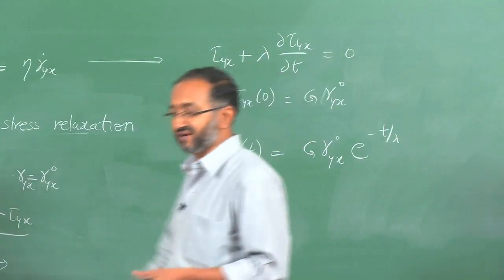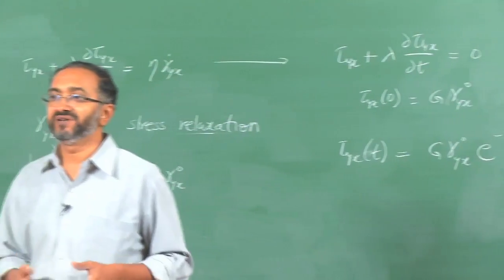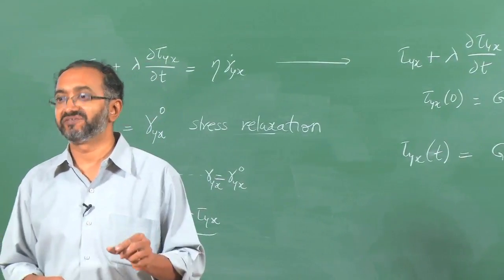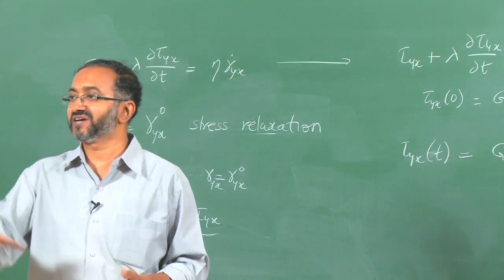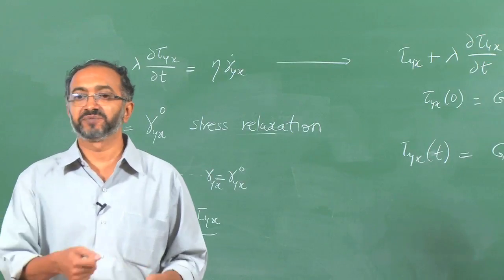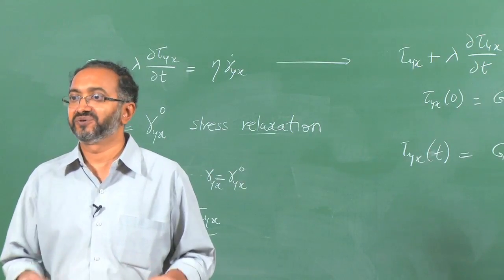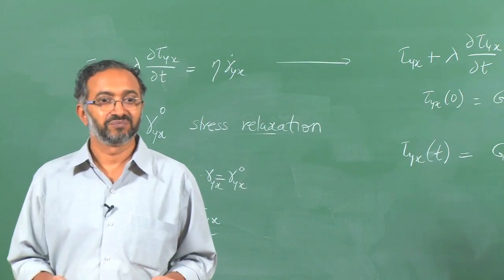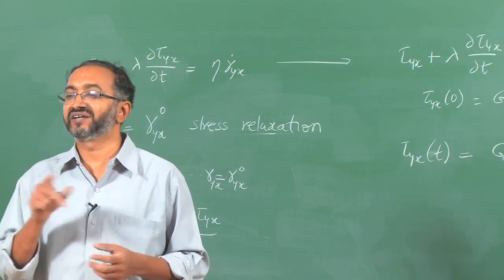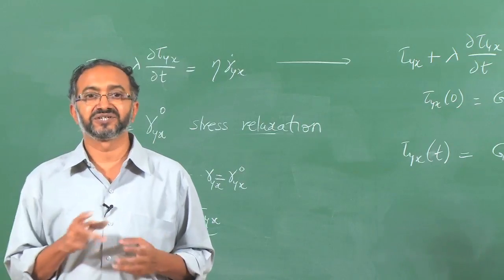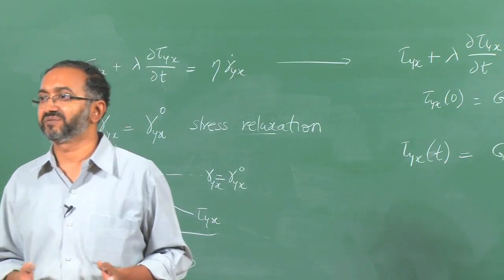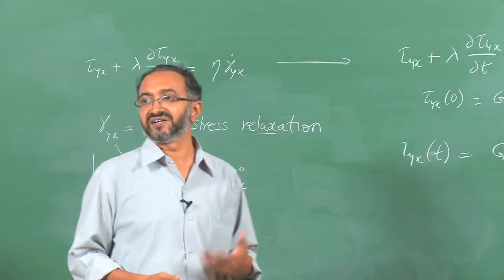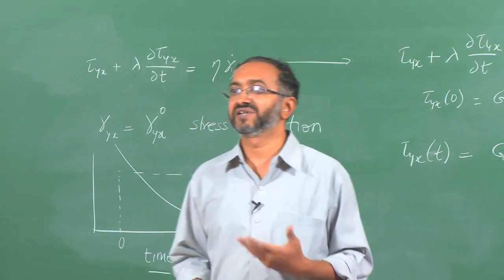So, the processes which may happen during yield at normal rates may happen over years at small deformation. So, let us say if 4% is the strain beyond which plastic deformation happens, if I deform the material to 2%, I would expect nothing to happen, right, it is elastic. But if I wait years and years, then with the grain boundary deformations and all that, those things which happen during plastic deformation will happen over much longer periods.